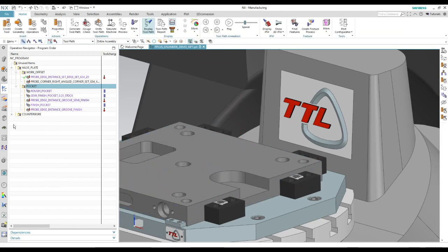This has enabled me to digitally view the entire machining program and make any required changes within the CAM session. This can all be done prior to running any NC code on the physical machine, thus saving potential downtime on prove out. Once I've measured the finished size, I can display the measurement, add a tolerance check, or perform any recutting using standard logic statements that can be outcut with the NC code.